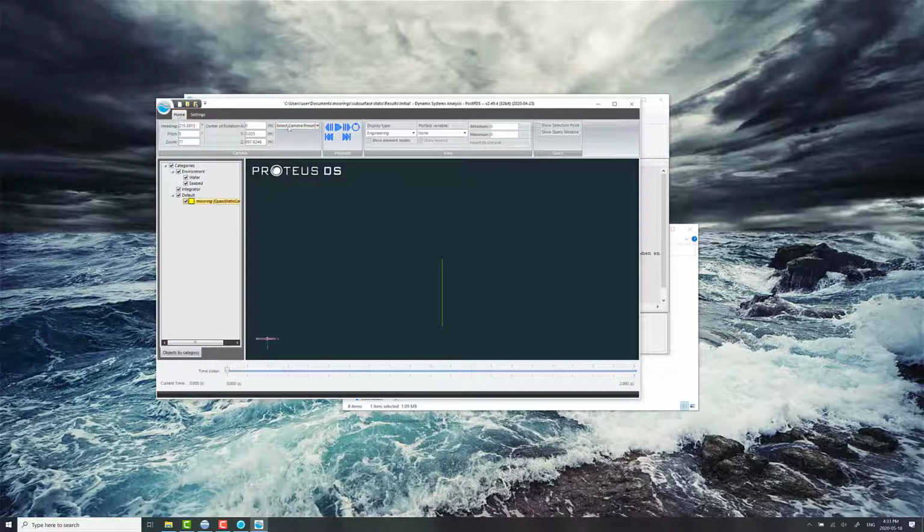So go back to home, and then if you select camera preset east, the current by default flows from the south to the north, and that's going to make the mooring deflect towards the right here. So we've got this east view with engineering view on. We can even show the nodes of the finite element mesh that have been generated automatically for us. Those aren't little floats, those white dots are the finite elements there. That just helps to give a sense of how many elements are involved.